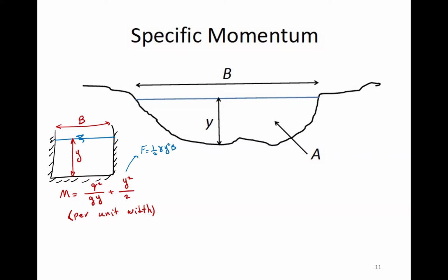That's a leftover from that hydrostatic force that shows up here. And then once we did the calculations, we had A over b in a rectangular channel, and A is b times y, divided by b, so it will be equal to y. So that was how we got there.